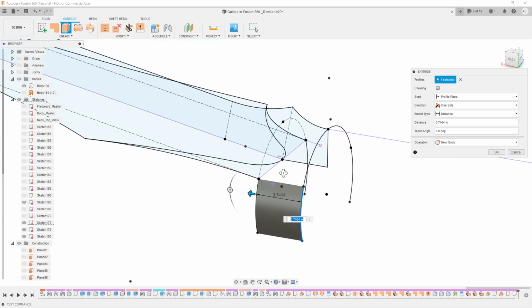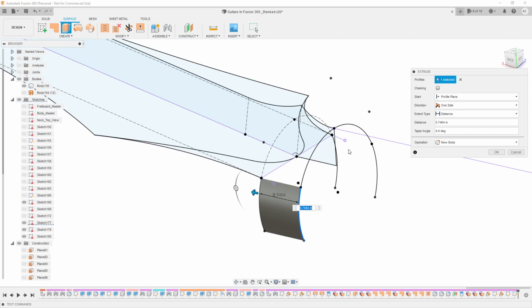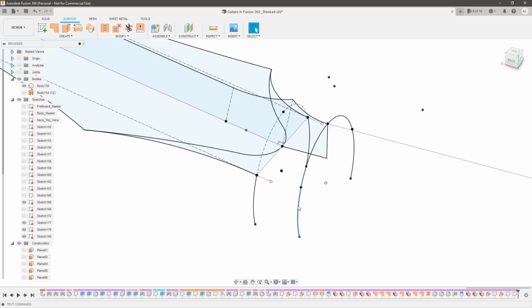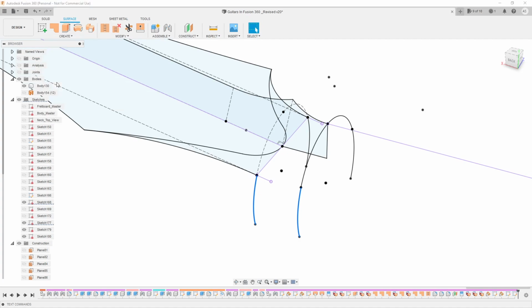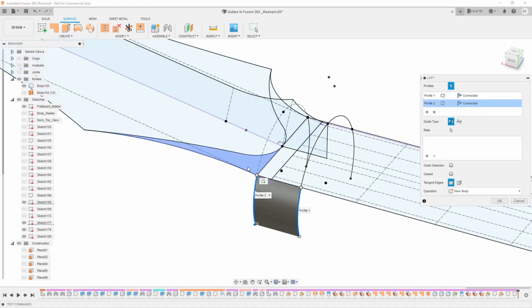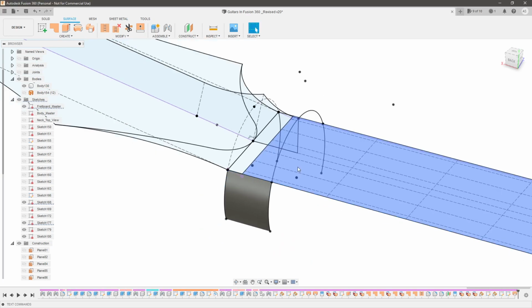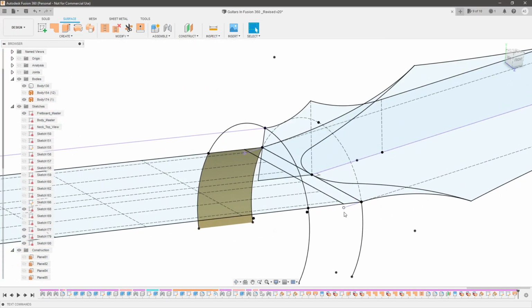So what I ended up doing was creating one more neck profile arc on the nut line and giving myself an additional helper surface or helper arc. That way I can simply loft between these two. So we can go create loft, bring back our fretboard sketch, and use this as a rail just to make sure everything stays lined up. Hit OK. And we're going to do the same thing on this side.